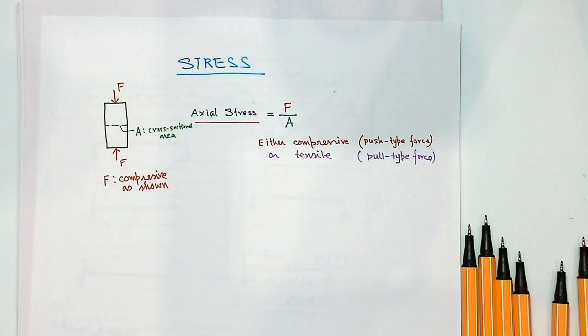The other thing you need to know is deformation. Deformation is critical because too much deformation can generate cracks, or the deflection could be too much, which makes it beyond its usable limits. For example, I would not be confident in walking on this floor if it was made up of some fabric. I put one foot and it dips down, another foot, it dips down. That would be too uncomfortable and beyond normal expected use for that type of structure. So although it is safe, I am not going to fall through that membrane, it is still not right deflection-wise.